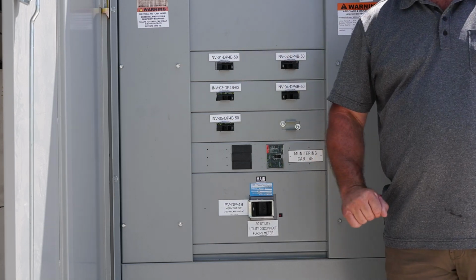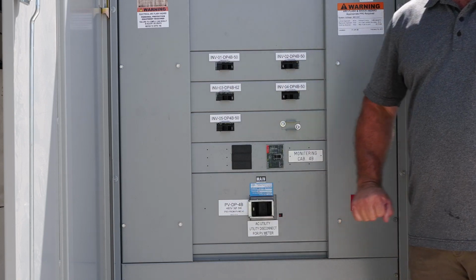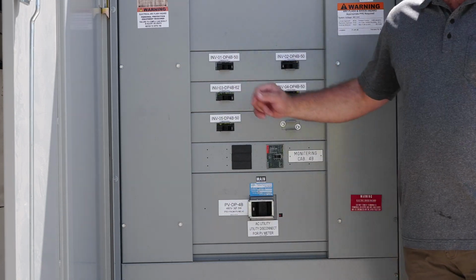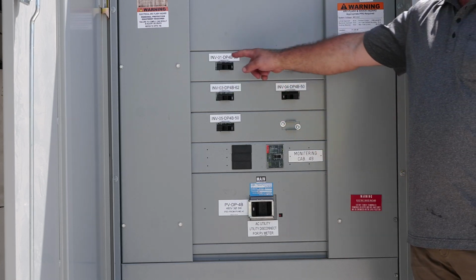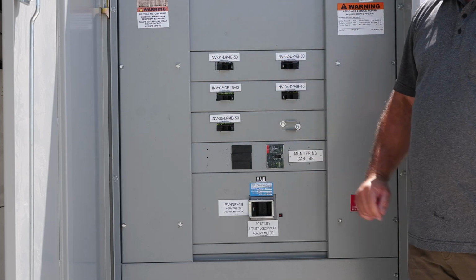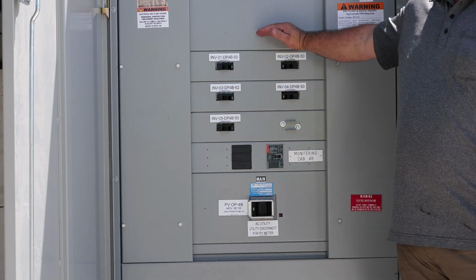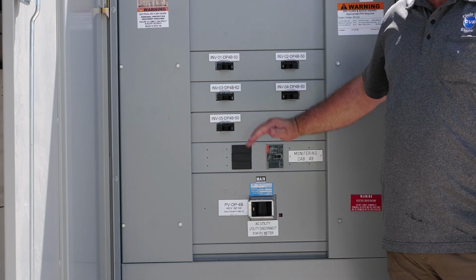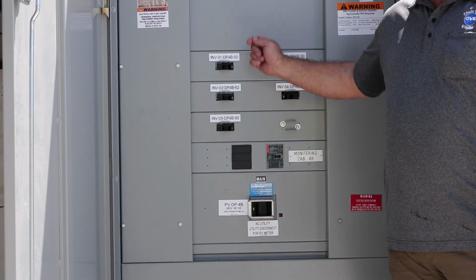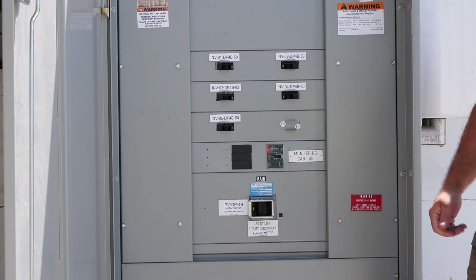So in case we have to shut down everything, we come here, we exercise the main breaker, and it's going to turn off. Each individual breaker, again, is labeled per inverter. Inverter 1, DP4B, it's a 50 kilowatt. Every inverter has to have a main breaker on the distribution board to disconnect from utility. Everything matches, labeling on the breaker and labeling on the inverter.